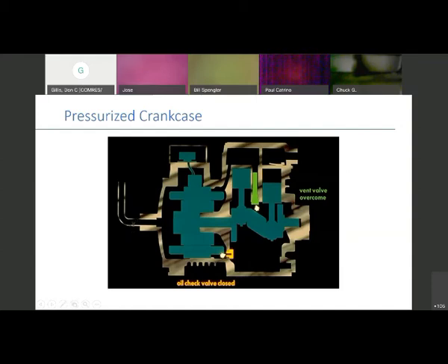Shut the suction valve off coming into the compressor, and we want you to turn this on. What you should see, if there's no blow-by, is your gauges will both go down at the same time, be fairly close to each other, and bottom out. If for some reason there is blow-by here, the gauge on the hose connected to this will start to go down, and then somewhere before it gets about halfway, it's going to stop while this side continues to go down.